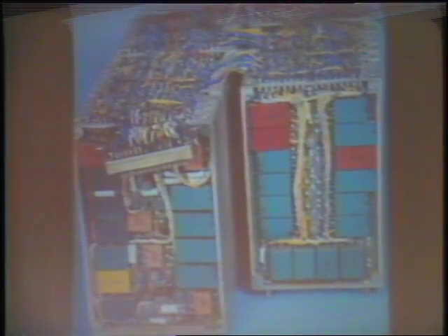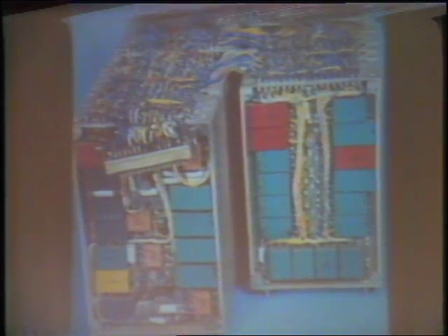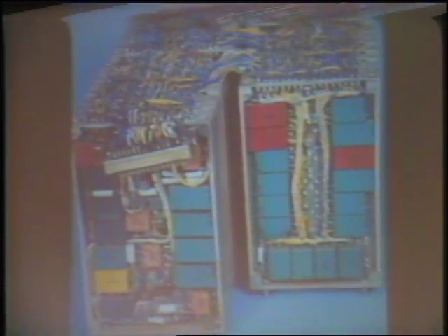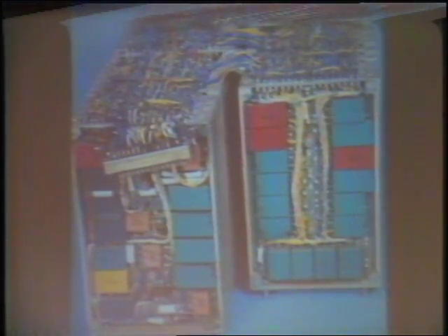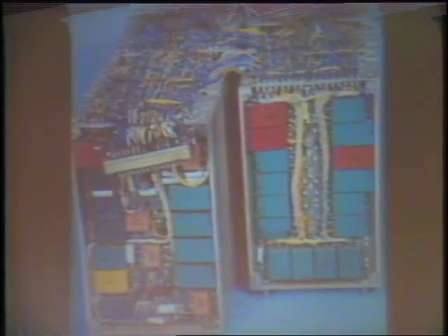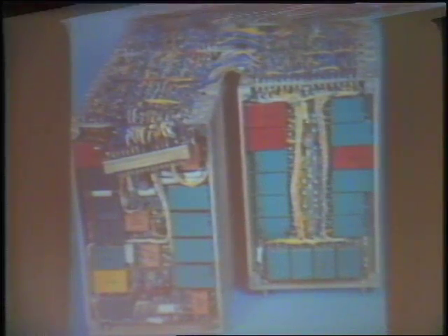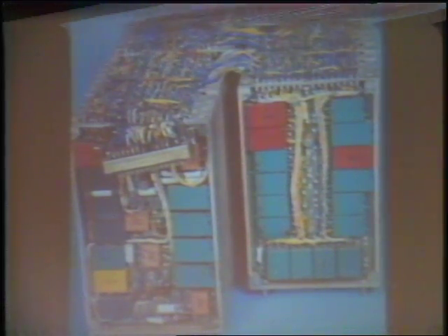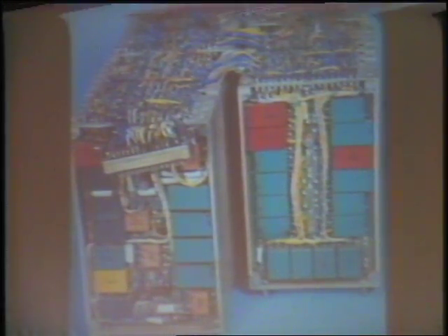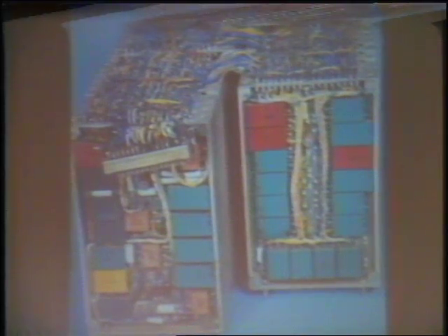This computer was about 4/10 of a cubic foot, weighed 26 pounds, and consumed 80 watts. But even before this first guided flight, we were exploring designs which would reduce the size and improve the maintainability of the system. The new design, eventually designated Mark II, repeated the architecture and logic design with improvements in circuits and packaging. Silicon planar transistors were used to replace the germanium junction transistors of the earlier version.